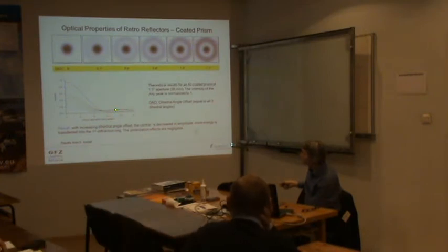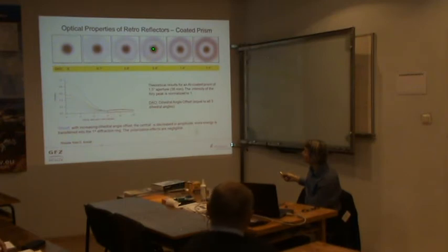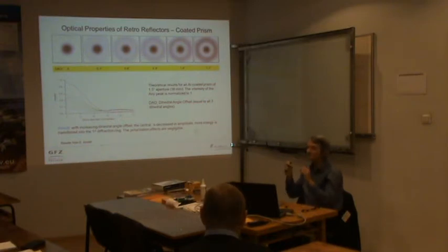But you see, the result is not just overwhelming. You will never get more than about 10% of the original energy which was contained in the central lobe in this first diffraction ring. So, this is one thing, and the other thing you have to take into account, seen from the satellite, which is moving there at a given velocity, the station which was transmitting and is receiving the signal will be located somewhere on the screen. It could be here or could be there, depending on the attitude of the satellite. That means what we see here, these 10% of the total signal are spread all along this diffraction ring. And this is the reason, together with the inverse proportionality of the fourth power of the satellite distance, that the signal getting back from outer space is so weak.